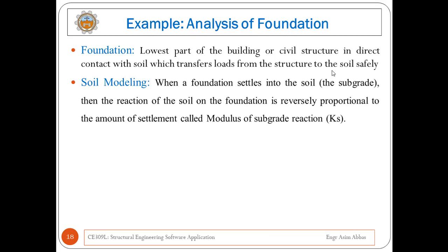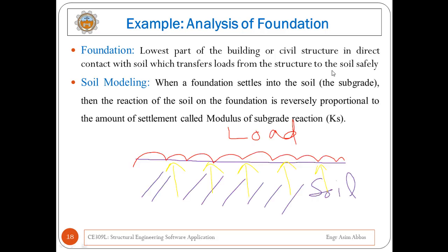This can be understood by analyzing the behavior of soil when it is loaded. Okay, in order to understand the concept of soil behavior, I will take a very simple example of how the soil behaves under load application. Let's suppose a certain magnitude of load is applied on a soil from a foundation. Initially, the soil will resist the applied loads, right? And this is shown by the opposite arrow. And this resistance is actually called the bearing capacity of soil.